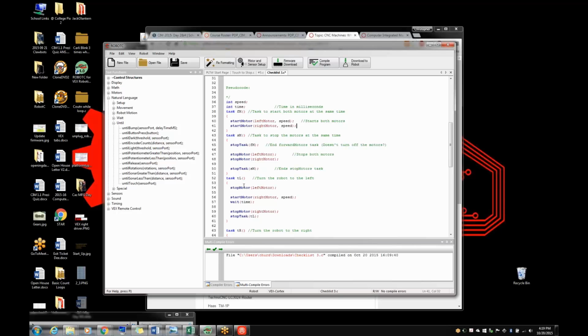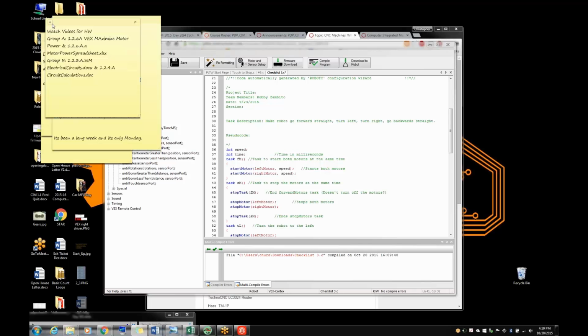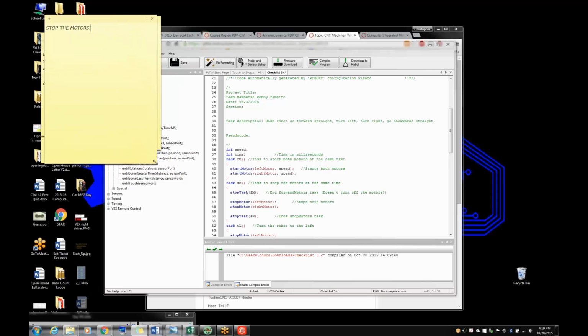Just because I asked an if statement to stop, just because I asked a while statement, just because I asked a task, anything, if I don't actually turn off the outputs, they'll keep doing whatever they were doing. Got it. Right. Yeah, we've noticed that with ours. And that's a good thing for the AGV, because usually if the AGV is turning one direction, even if it's lost the line, it'll keep going in that direction until another if statement one way or another gets met. Otherwise, if you had it written like you really should, with an if, an else if, and an else, as soon as it loses the line, it would stop. It just wouldn't do anything.